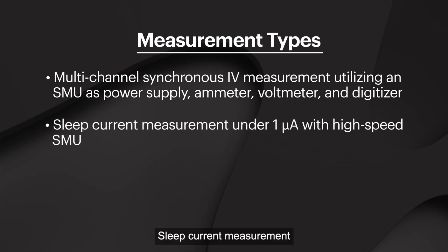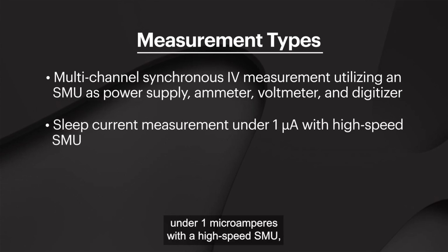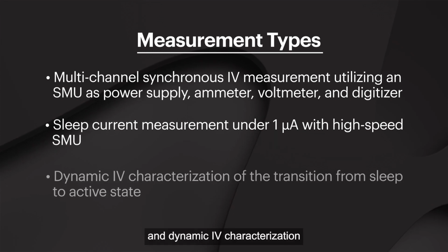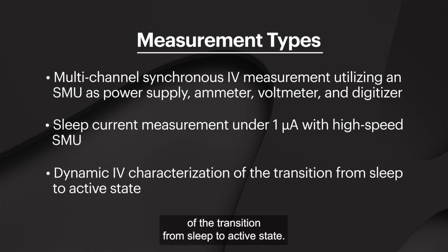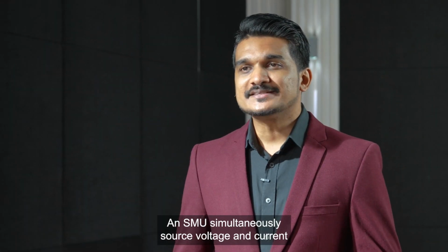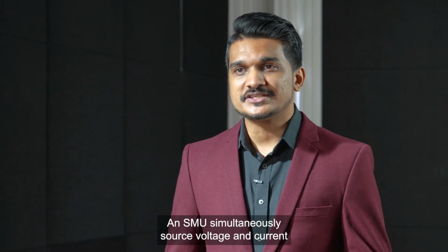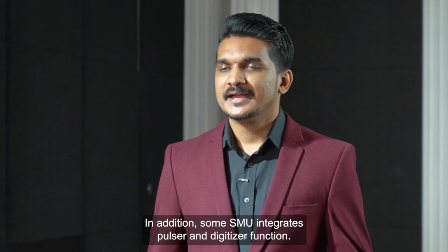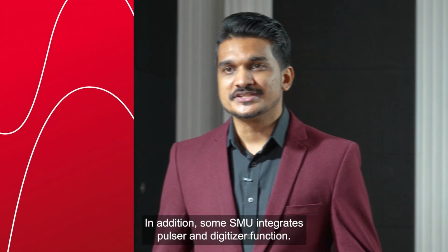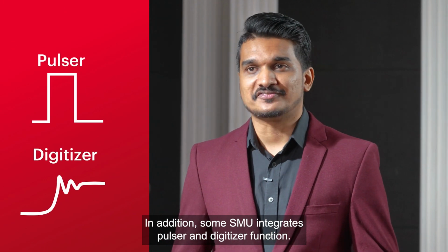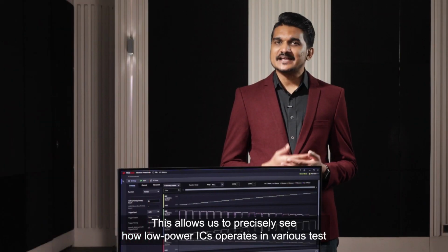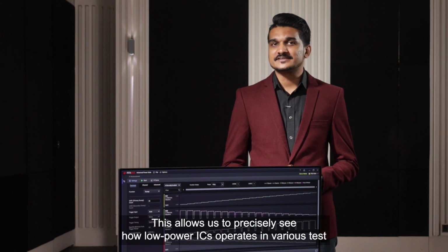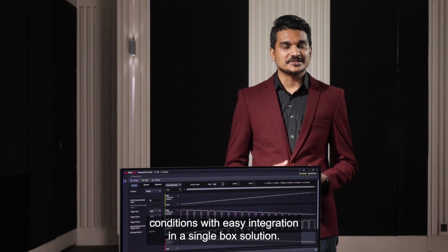Sleep current measurement under 1 microampere with a high-speed SMU, and dynamic IV characterization of the transition from sleep to active state. An SMU simultaneously sources voltage and current while measuring voltage and current precisely. In addition, some SMUs integrate pulser and digitizer functions. This allows us to precisely see how low power ICs operate in various test conditions with easy integration in a